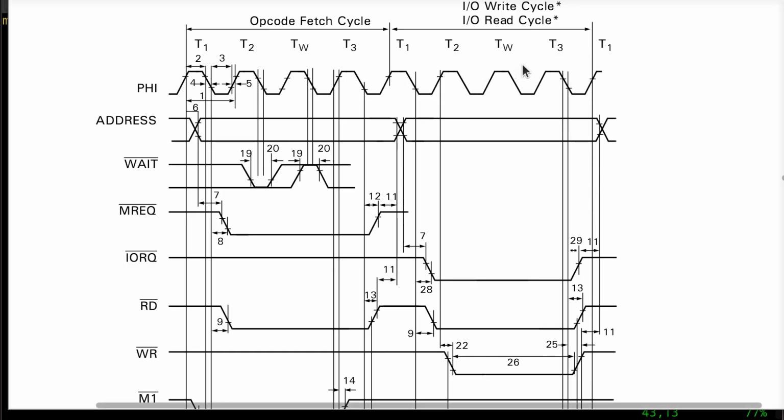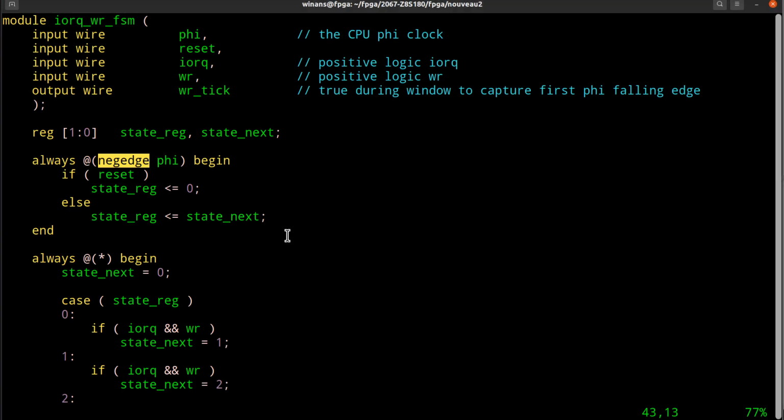After the next falling edge, specifically, I deassert my tick signal, and then I keep it low until the next transaction. So what I'm going to do is identify this cycle right here, which is a wait state for an IO operation, but it's T3 if I'm writing to memory, because that doesn't exist and it's the same number of edges. Okay? So that's what I want to do.